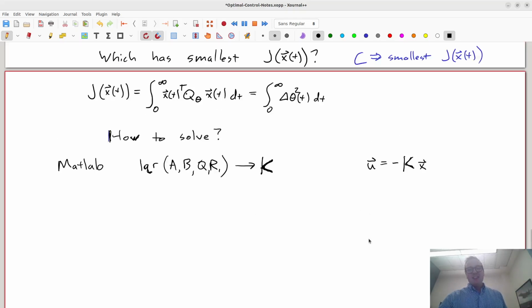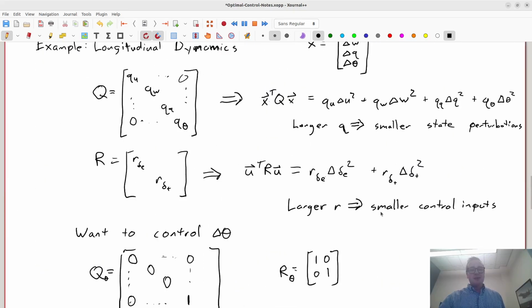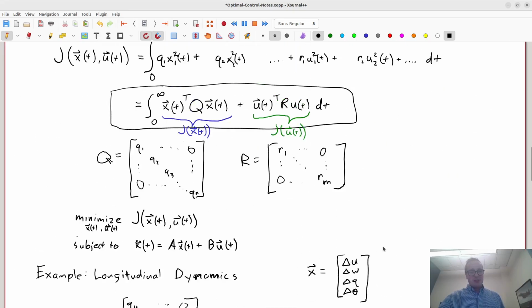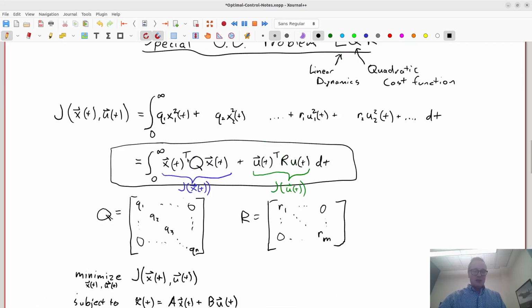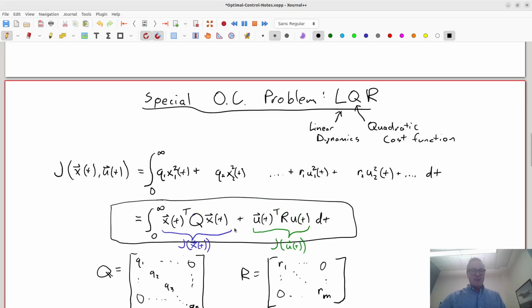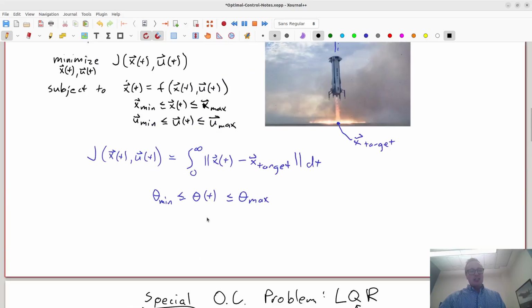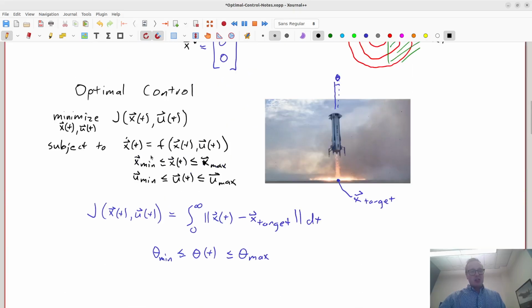Now, when you're watching this the first time, it'll probably seem pretty normal, like, oh, that's what controls is, u equals negative Kx. This is not true if anything is different about the problem formulation. If we don't have this quadratic form for the objective function, or if we have constraints in addition to the dynamics constraints, any of those will make this not have a linear optimal control solution.